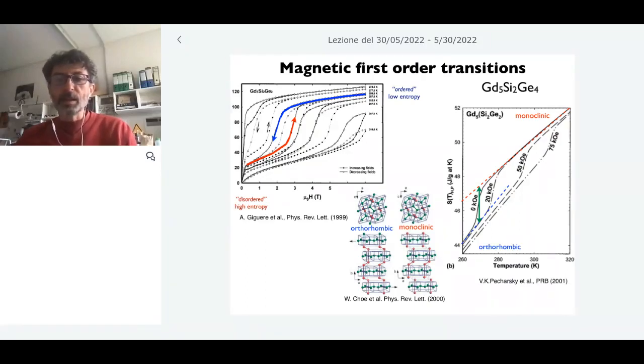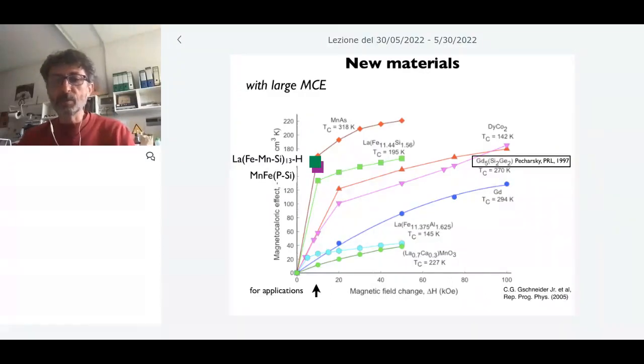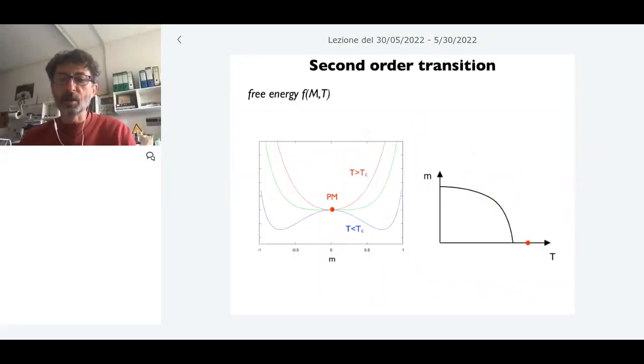Not all materials you can do this with very easily, because a few of these magnetocaloric materials do have hysteresis, because also in this case, as we have shown for nickel, manganese, gallium, there is a phase transition involved with the magnetization. Maybe this is moving a little bit fast. This is just a picture to show you what are the typical materials that are nowadays being investigated for this magnetocaloric refrigeration.